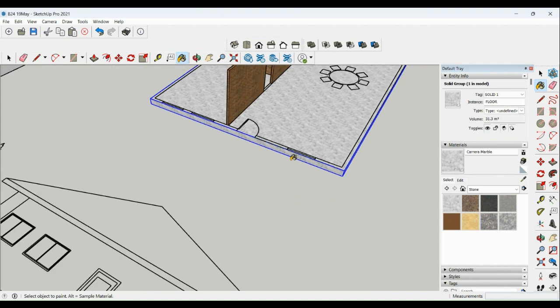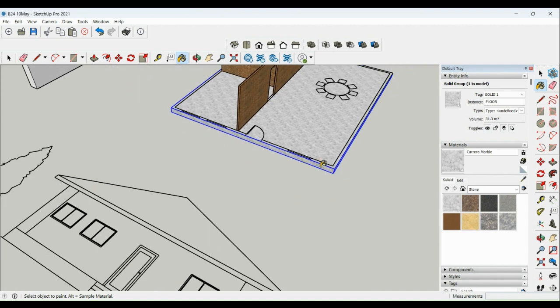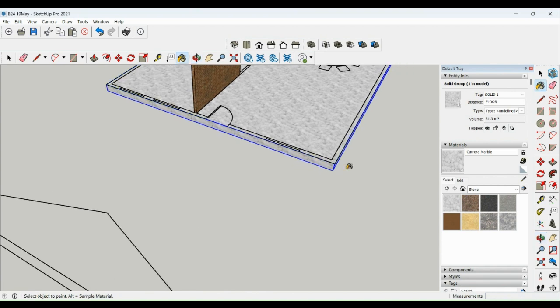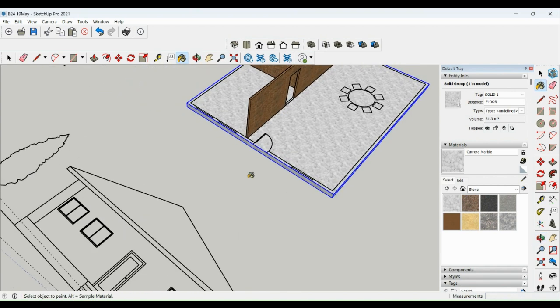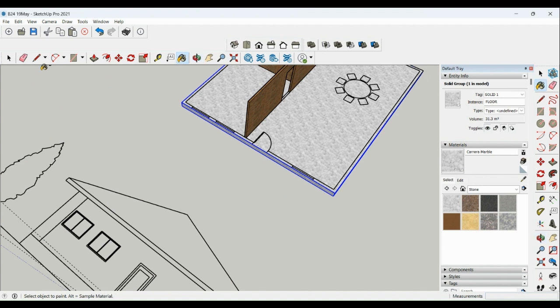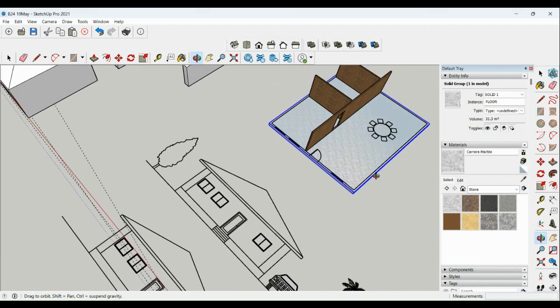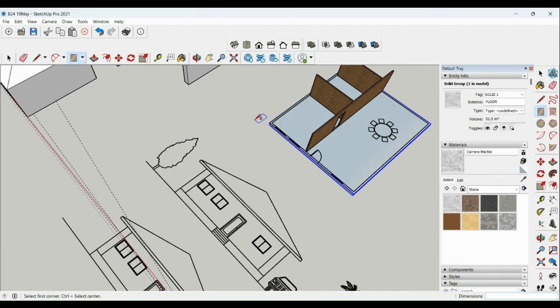I can make a wall, and maybe I just subtract something, right? I will just subtract it. So let me create something. Let's say I'll draw a rectangle from here up to here. Then what will I do? I'll make another rectangle. I will offset, a distance of maybe 500. Enter. And I'll click this and offset going outside.